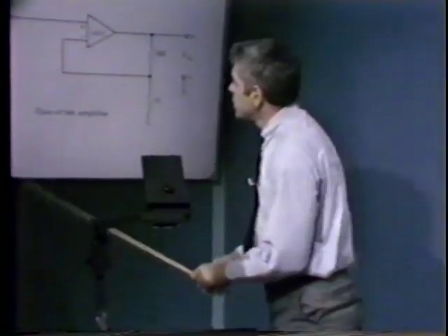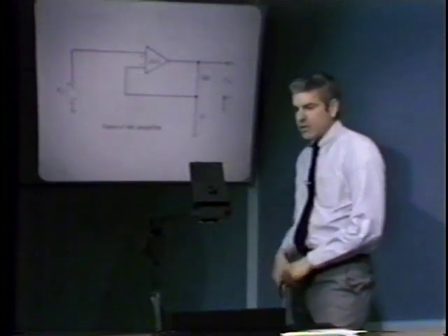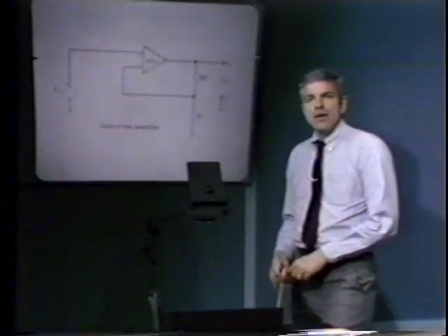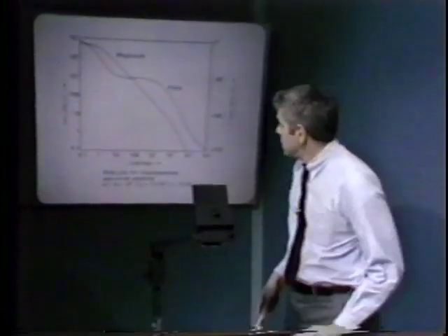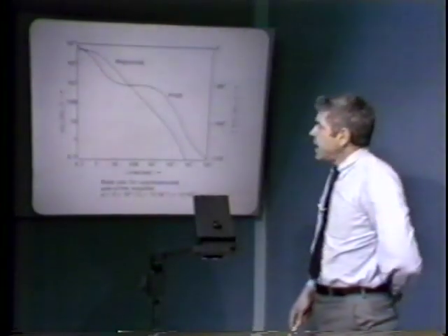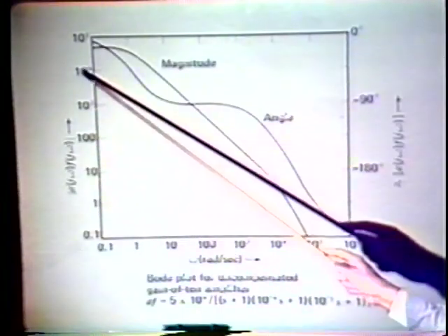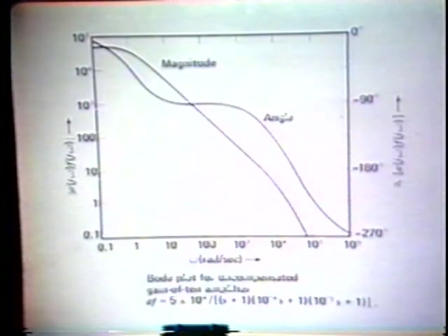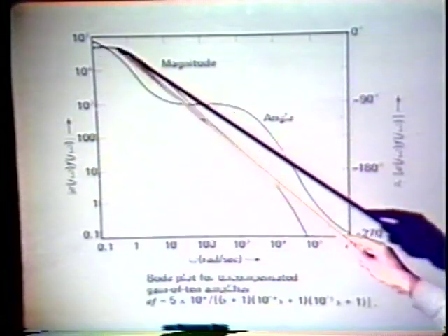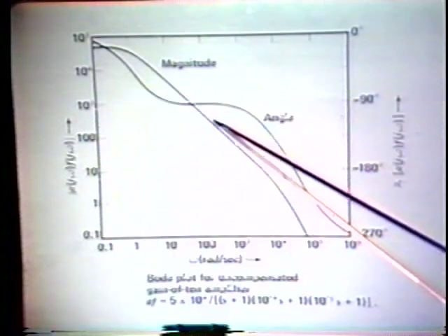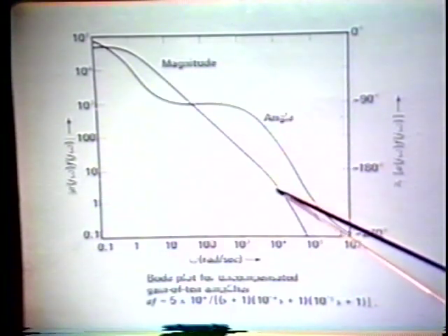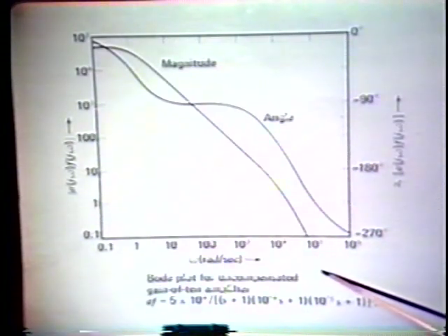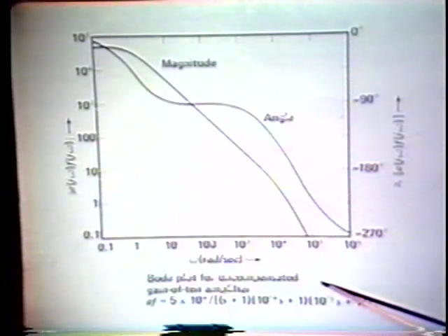If we once again look at either our operational amplifier or the block diagram that we've just seen, we recognize, of course, that the loop transmission for this system is simply 1/10 of A of S, since F is 1/10 and is frequency independent. We can plot that loop transmission in Bode plot form, and this is the result. Since A of S itself has a magnitude at DC of 5 times 10 to the 5th, the AF product will have a magnitude of 5 times 10 to the 4th, reflecting the value of 1/10 for F. We have a first pole at 1 radian per second. We then drop off with a 1 over S, 1 over frequency roll-off until we get into the second pole at 10 to the 4th radians per second, and eventually, well below unity gain for the loop transmission, we'd get the third pole, the one located at 10 to the 5th radians per second.